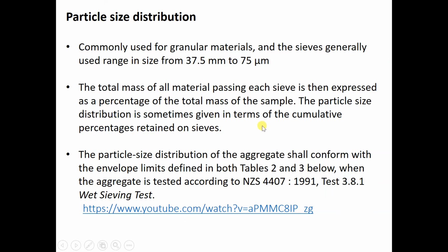Okay, so there's a particle size distribution. So we need to run the sieve analysis on the site. Usually on the site they have the soil lab. They are usually checking the aggregates that have been sent from the quarry to the site. So they need to do the testing and make sure that, if it's not according to the spec, they need to remix it. It's just for checking.